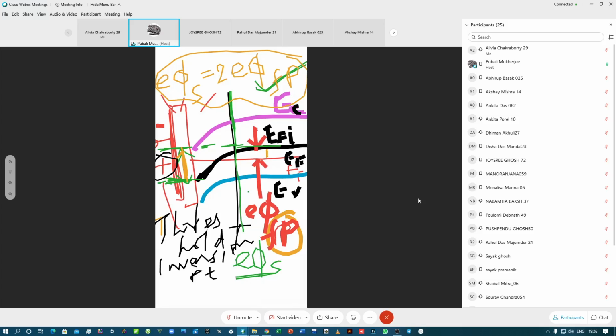And what is the significance of this threshold voltage? Threshold voltage is the voltage where a significant amount of accumulation of negative charges has taken place at the oxide semiconductor interface, so that a nice induced channel of negative charges has been created. Now the application of a positive drain to source potential leads to the flow of a drain current in the device. So this is called the threshold inversion point and threshold voltage. Is it clear, students?